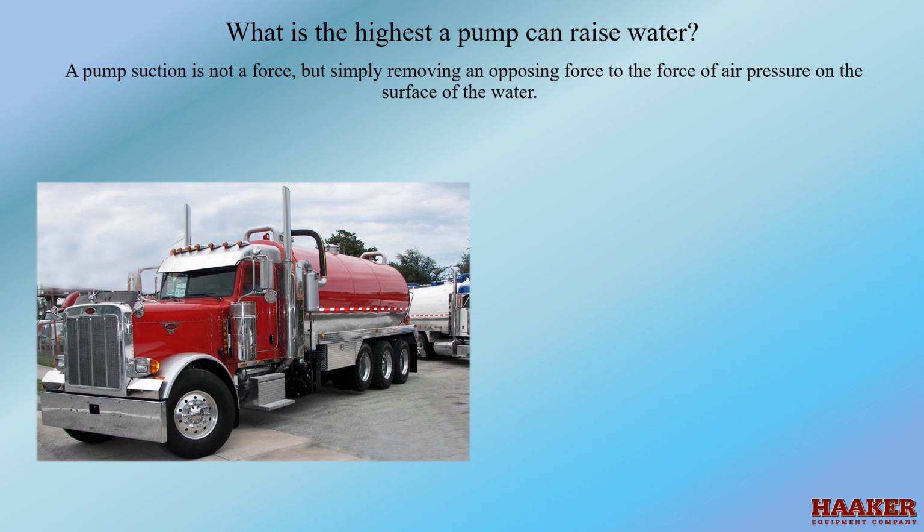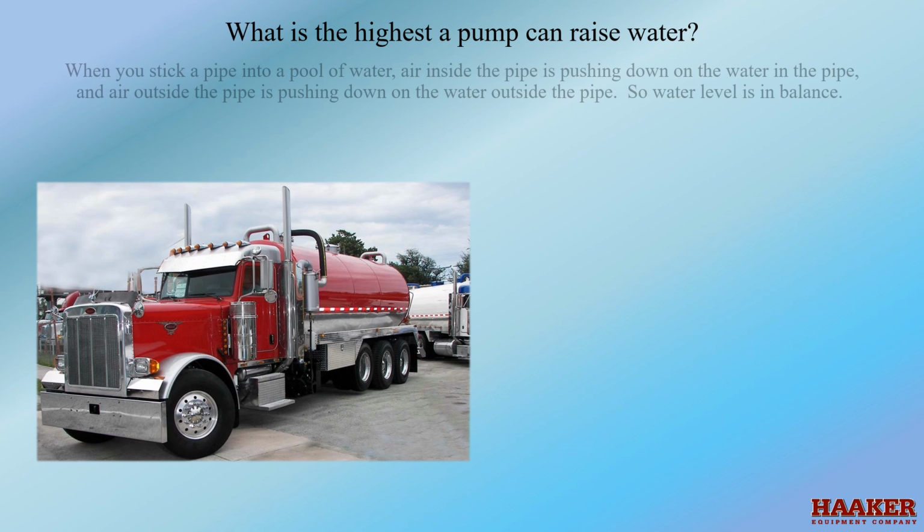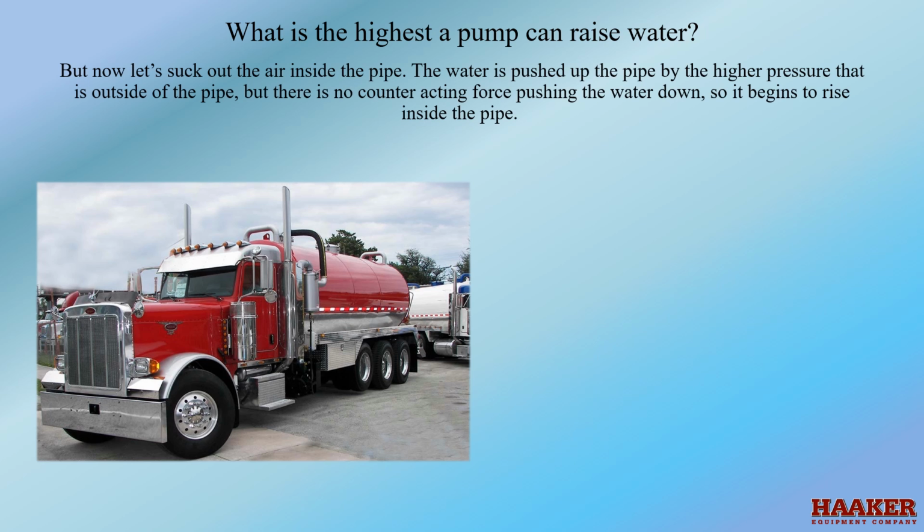A pump suction is not a force, but simply a removal of an opposite force to the force of air pressure on the surface of water. When you stick a pipe into a pool of water, air inside the pipe is pushing down on the water in the pipe, and air outside the pipe is pushing down on the water outside of the pipe, so water level is in balance. But now let's suck out the air inside the pipe. The water is pushed up the pipe by the air pressure that is outside the pipe, but there is no counteracting force pushing the water down, so it is being raised inside the pipe.